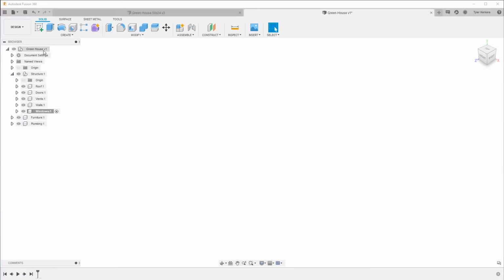And then that makes it really difficult when you have a list of, I don't know, 25 different sketches under your top level assembly, and you have no idea what components they relate to. So the more organizing you can do from the start, the better. In projects where I really don't understand where I'm going, oftentimes I just start creating bodies and I just start designing. And then in a lot of cases, I'll get like 25% done with the project that I've started, and I'll go back and almost restart the project because I think this part is so important. Like, okay, now I have scope of where I'm going. Let's go back and reorganize components and start fresh, start again.